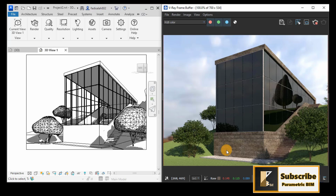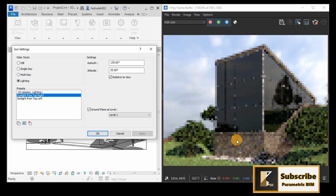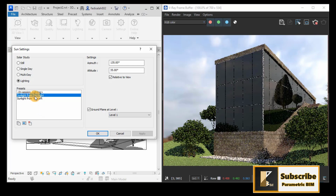So the lighting of the sun here is related to the lighting of the sun from Revit. If I come here and go to sun settings, and for example set the sunlight from top right and apply this, you can see that the interactive mode will change to the same view, because the sun is in the top right, as you see.